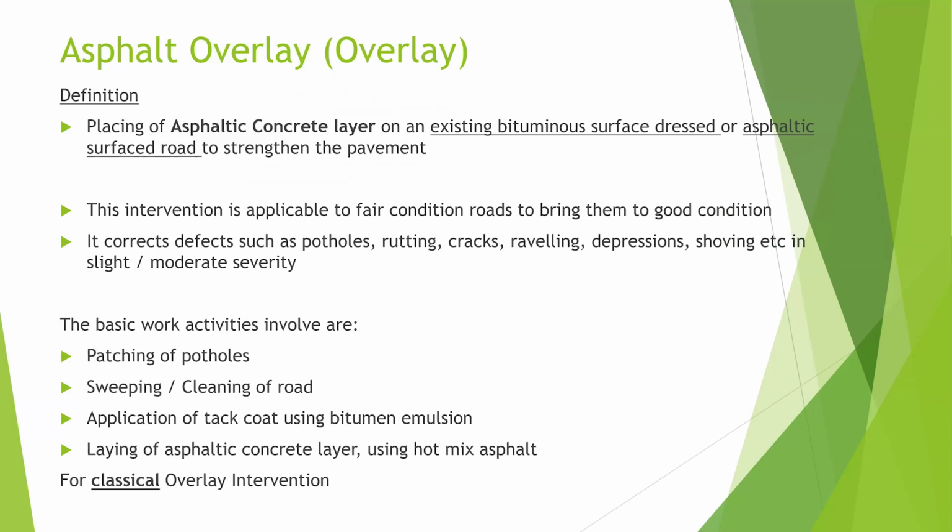Now, by definition, classically, an overlay is the placing of an asphaltic concrete layer on an existing bituminous surface dressed or asphalt surface road, to strengthen the pavement. So you are placing an asphalt concrete layer on an existing BST or a bituminous surface dress, or an existing asphalt surface road to strengthen the pavement. Now, this intervention is applicable to fair condition roads to bring them to good condition.